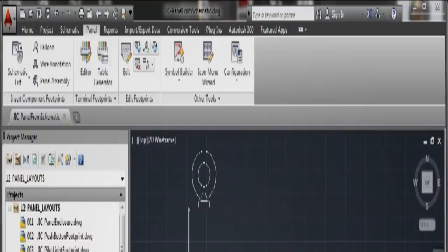So you might draw the schematic first, or you might draw the panel first. Which would you do? It's panel first and create the panel footprint. You then create the schematic from that footprint. And then when you want to create another panel, you know that you've got those components on the schematic already, so you can bring them in to the new panel, maybe a second panel, a third panel that you're creating on this particular project.